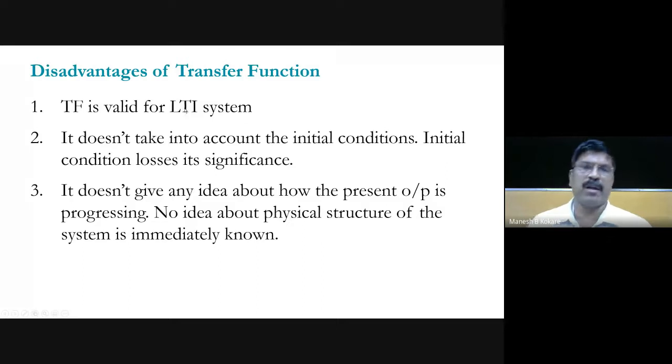We have studied what is a linear system, what is a time invariant system and a time varying system, and then what is an LTI system, right? So the first disadvantage, or limitation we can say, is that the transfer function is valid only for an LTI system, right? The second disadvantage of transfer function is that it does not take into account the initial condition.